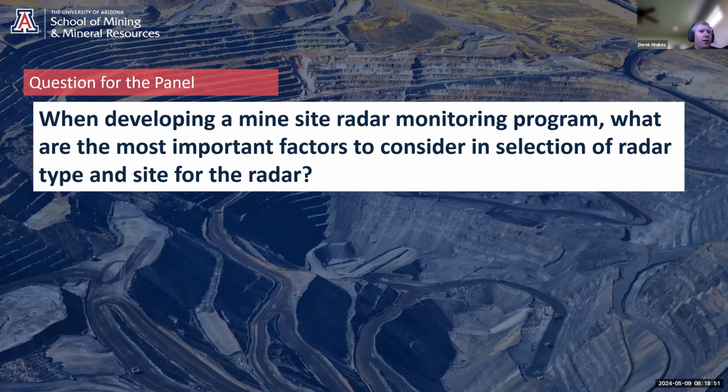So understanding vector loss of movement and how that will actually be recorded on these units is important as part of that siting assessment. And then site traffic and accessibility: you want to make sure you're not near blasting or hauling, or if you are, that you can turn these units off or decommission them temporarily. But you also want to have access for maintenance and things of that nature. So it is a process, a lot of things to consider, but I'll leave it there.